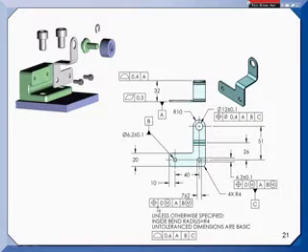They're not real critical. I have a general profile tolerance of 0.6 millimeters, so I'm giving you a very generous tolerance all the way around those surfaces. If you start calling these out as datum features, then I'm going to have to tighten the position of this hole and the position of this hole in order to get something similar to what I'm getting out of this design. So the cost of the part is going to go up.